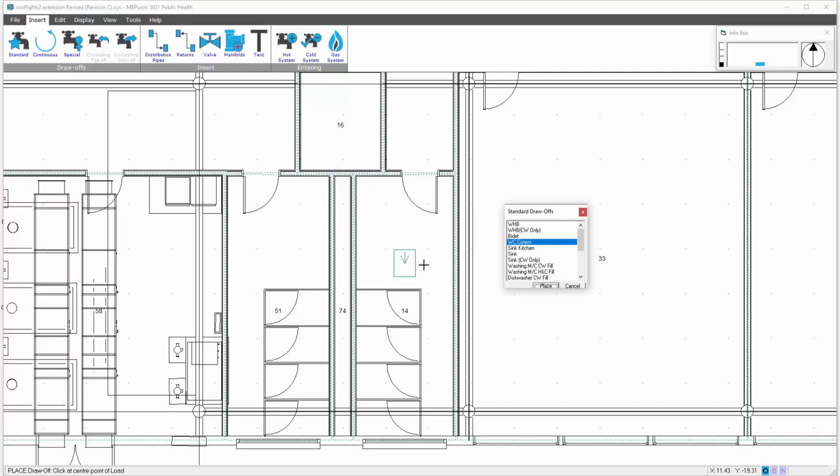A right button click while it's floating around on the end of your mouse rotates it 90 degrees. You can alter the rotation in display options called right button twist. So you can vary that rotation. Click once to place the appliance. Right button click twice and allows you to create a mirror image of the previous appliance. Press escape and then cancel the command.